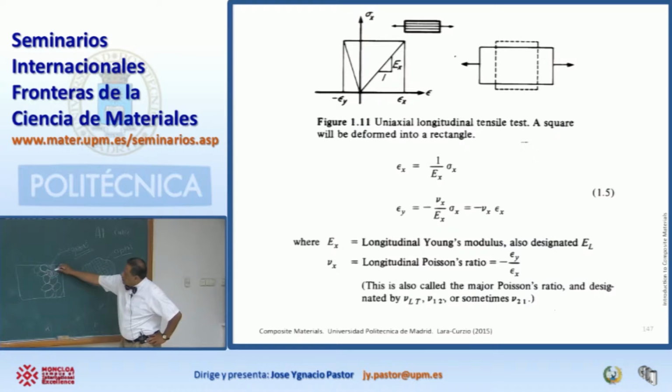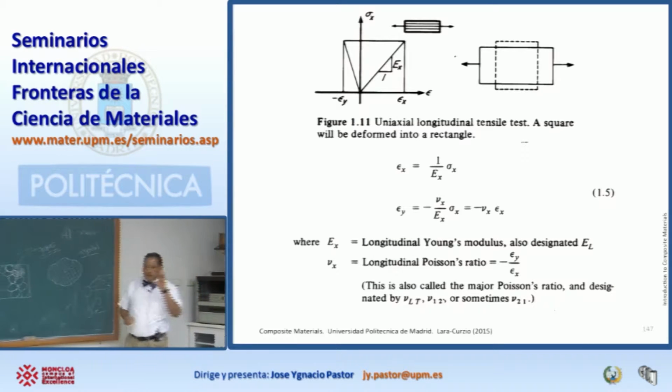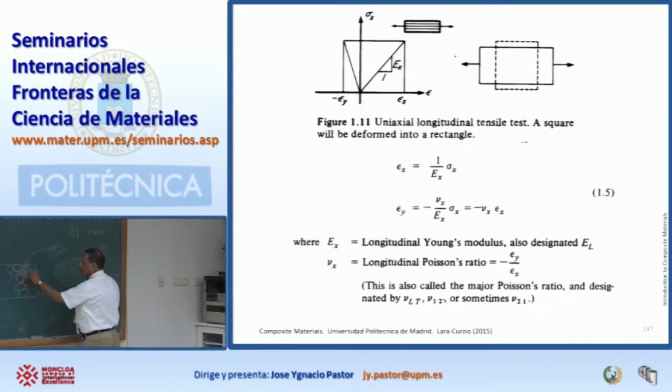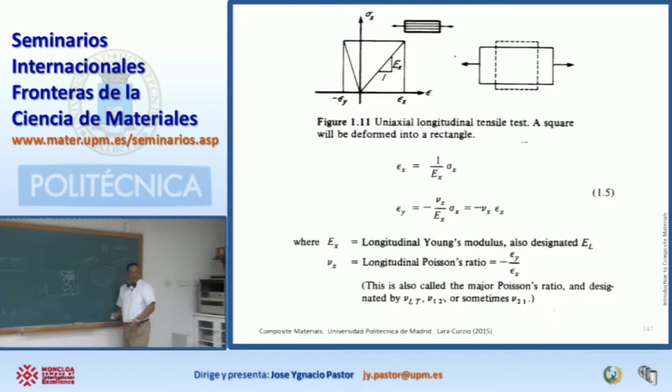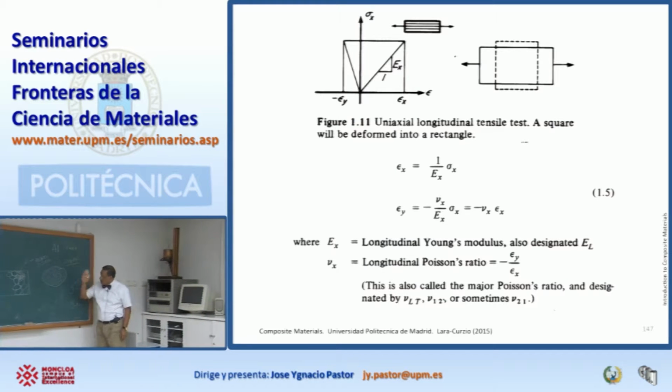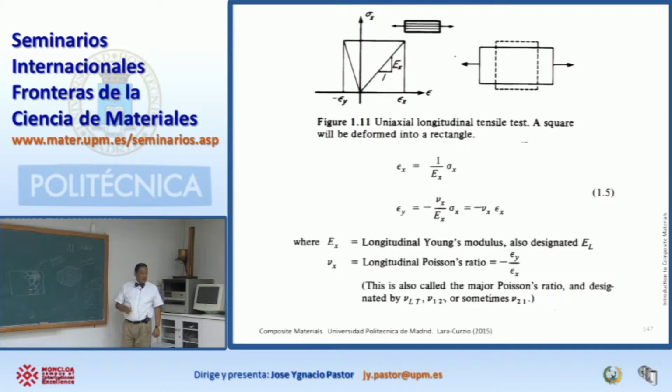And the reason why we have grain boundaries is because the organization of the grains is going to be different at the grain boundaries. If you could remove a single grain, this will be a perfect crystal. All the atoms are going to be perfectly aligned. And you're going to see this in ceramics, in metals. Any material that crystallizes in an organized way is going to have this type of structure.